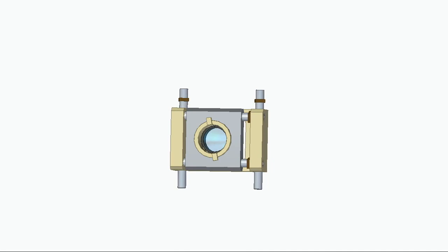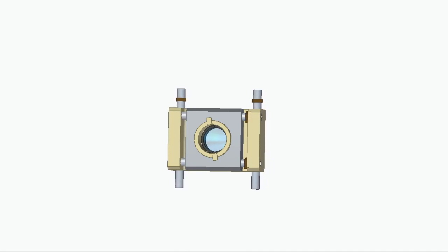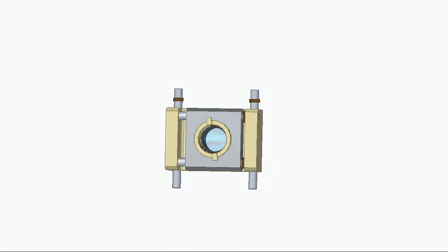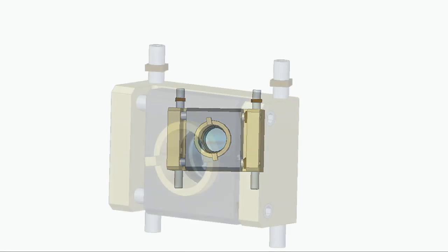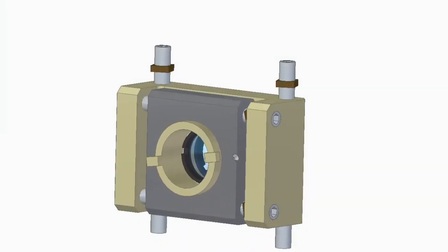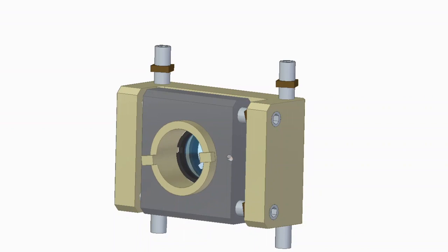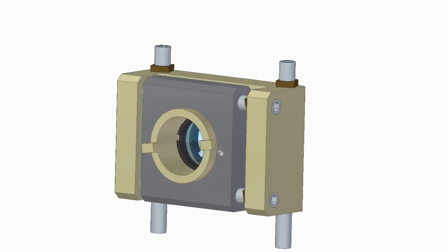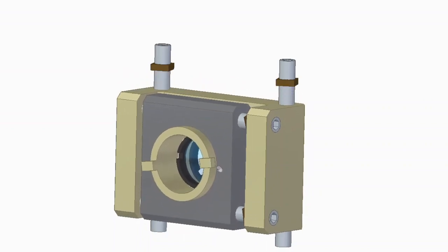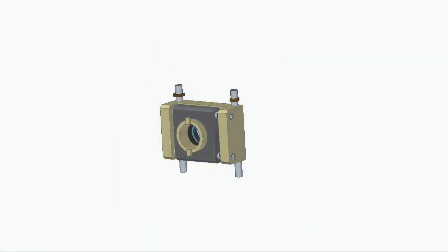The laser and lens must be precisely aligned for optimal performance. The mounting mechanism must be able to adjust their alignment, which is accomplished using precision threaded rods. Rotation of the rods allows up to 1 mm of travel in either direction along the X and Y axis. The rotation of the cylindrical lens housing permits travel along the Z axis.